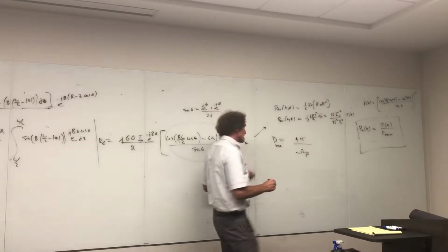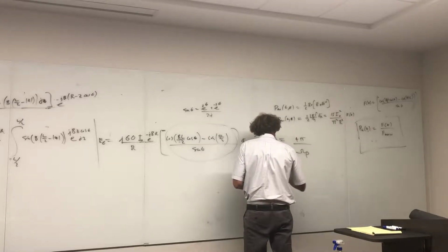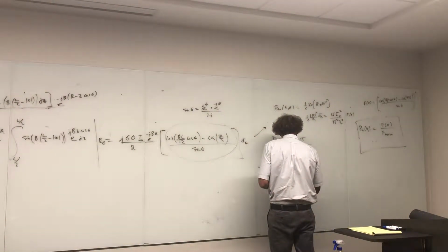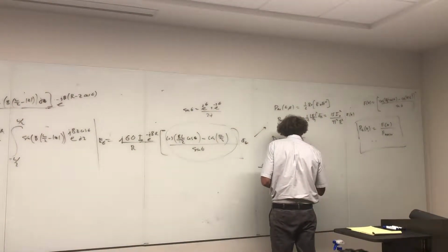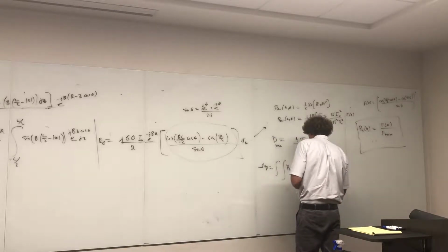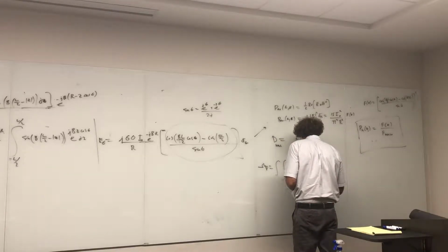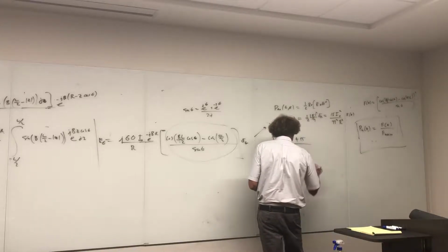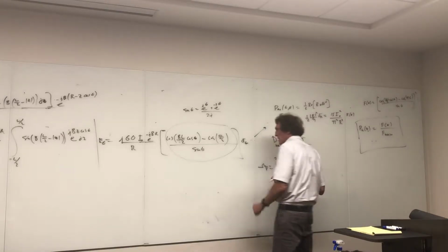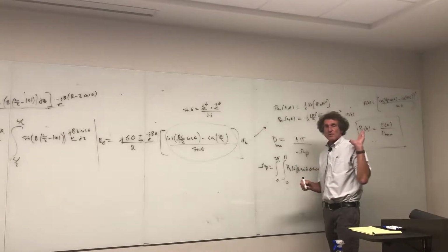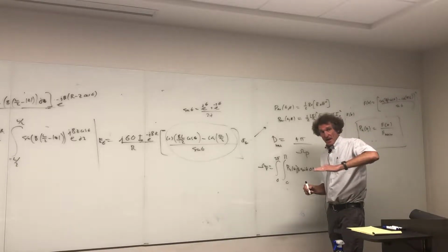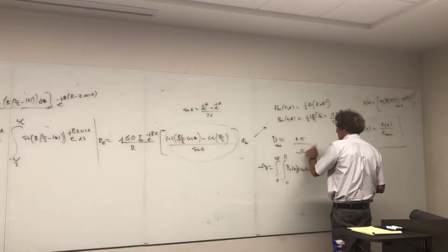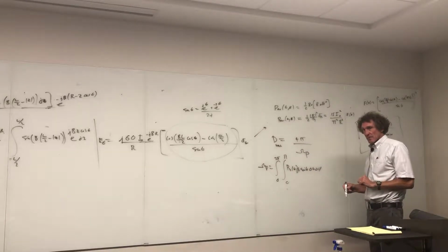Please hear me on this one. The solid angle would be that integral of the normalized power density, P normalized, as a function of theta and phi, really just a function of theta in our case, times the sine of theta, d theta d phi. Now phi will go from 0 to 2 pi almost always. Theta goes from 0 to pi for any kind of a half-wave dipole. For monopoles, it'll only go from 0 straight up to 90 degrees. Monopoles are above the Earth, and I'll cover that later. But this will give you the solid angle that goes here, and that's the maximum value directivity.